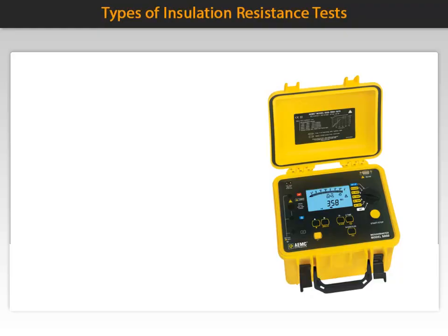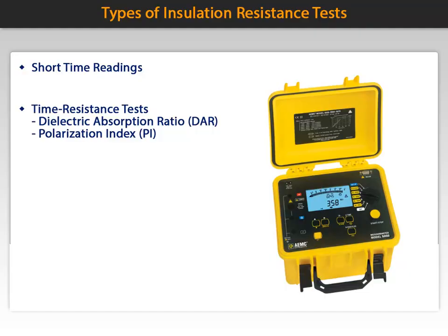There are three basic types of insulation resistance tests. Short time readings usually are 60 seconds in duration. Time resistance tests, which include dielectric absorption, or DAR, or polarization index, or PI. Lastly, there are step voltage readings, which are mostly used for DC overpotential testing and can be used at insulation resistance test values. We'll spend more time on each of these.